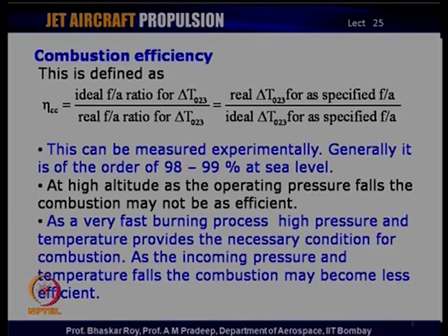So, the necessary condition for good combustion is that you have reasonably high pressure. That of course signifies the necessity of having a compressor in front of the combustion chamber. So, incoming pressure and, as a secondary requirement, incoming temperature, if they fall, the combustion may become less efficient, and